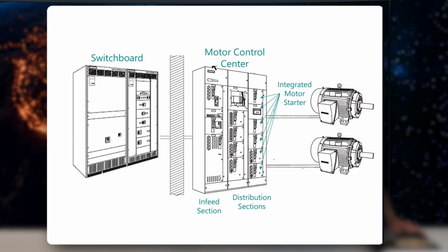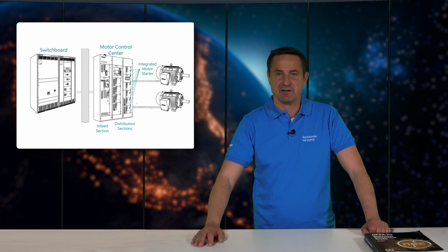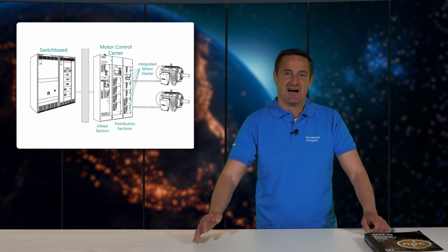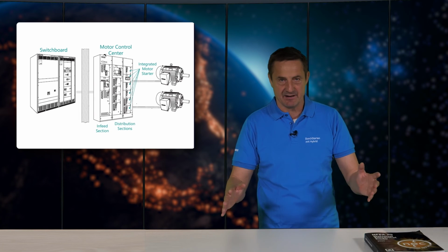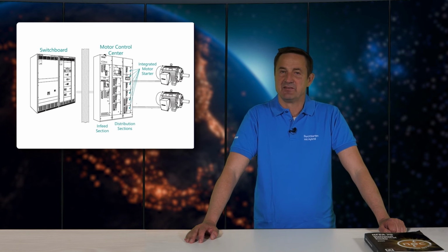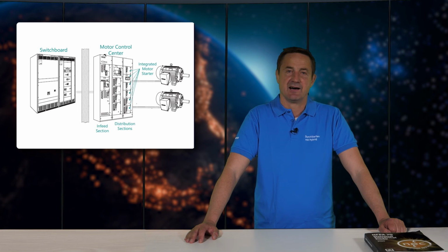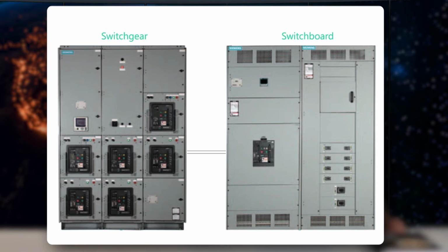These electrical cabinets, which are specifically designed to distribute the main power to motor loads and provide the entire motor control and protection, are defined as motor control centers in the NEC and better known as MCCs. The safety standard for these MCCs is the UL 845, applicable to single or three-phase motors up to 600 volts AC and 1000 volts DC motors.